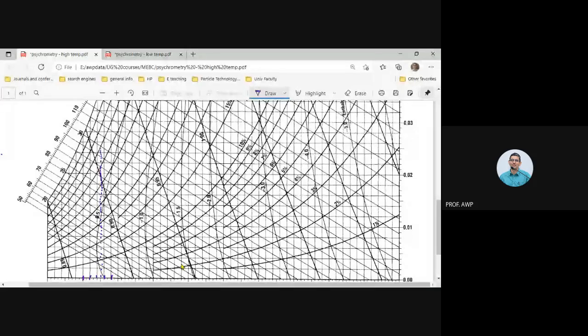And our dew point is 30 degrees centigrade. That means if I cool this air, water will start condensing at 30 degrees centigrade. That means the humidity must be such that if I cool that air, it will become 100% saturated at 30 degrees centigrade. Therefore, the incoming air must have this kind of composition. Do you agree with that?